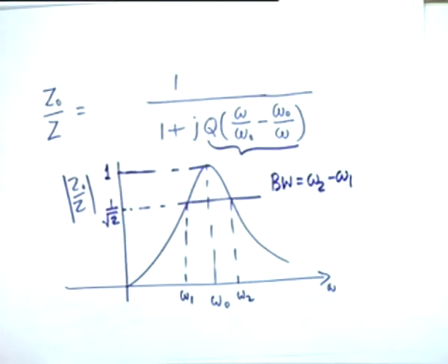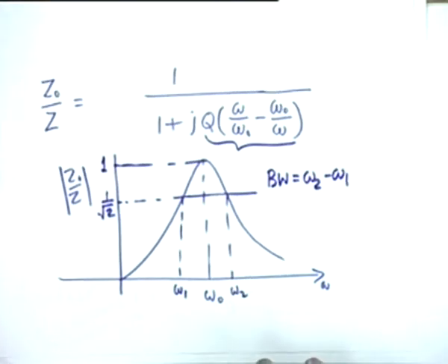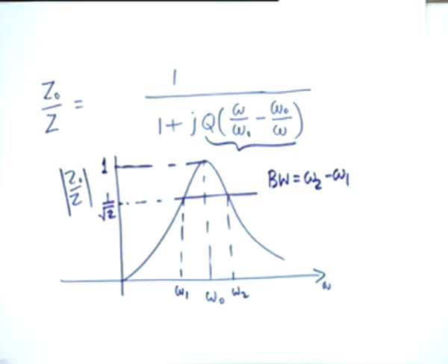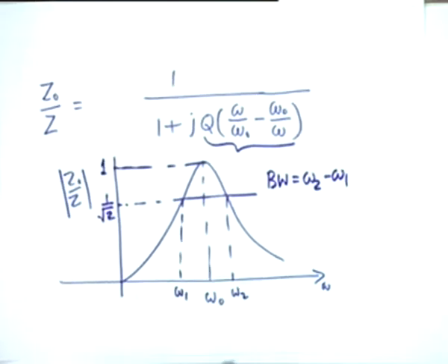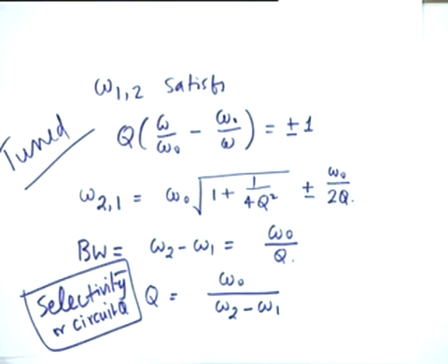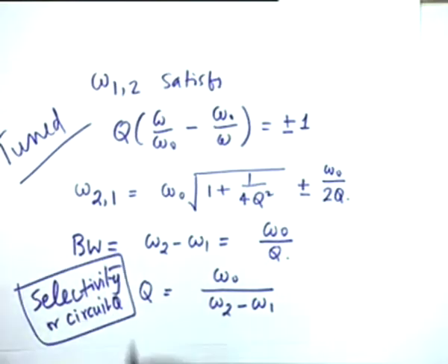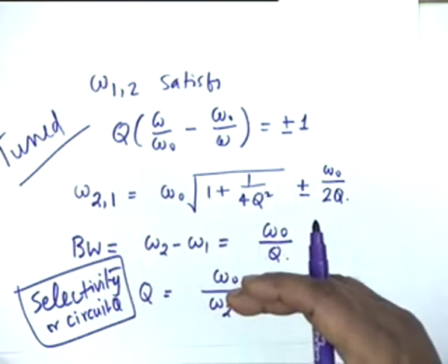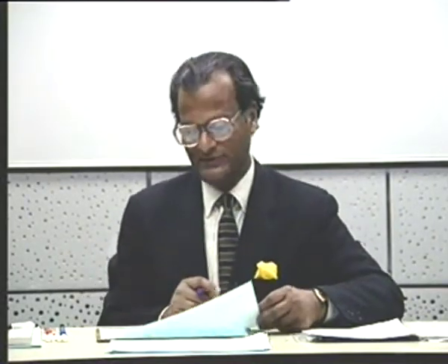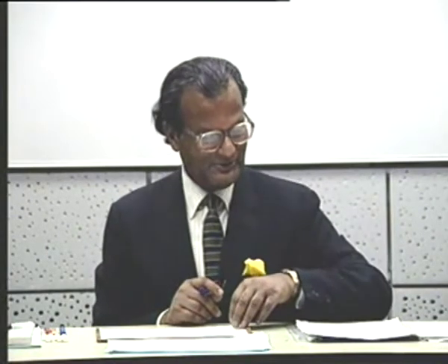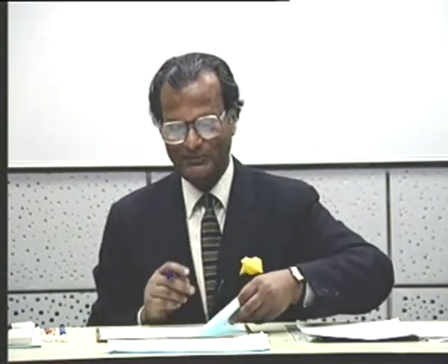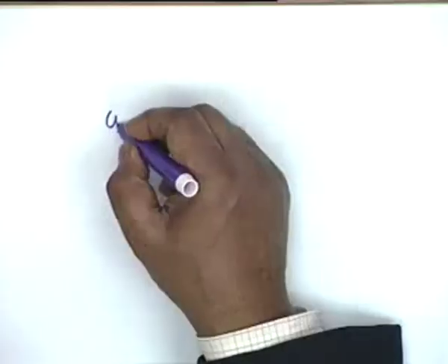The basic condition for resonance is that the current and voltage are in phase. That's right. The phase difference between current and voltage is 0. This is defined as the condition for resonance. All right. This is why the voltage maximum across an inductor is not necessarily at the resonance frequency. That is not a condition of resonance. Voltage maximum across a capacitor occurs at a slightly lower frequency, and that is not the condition of resonance.